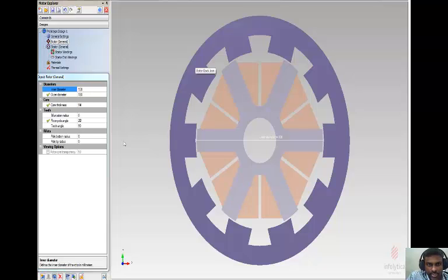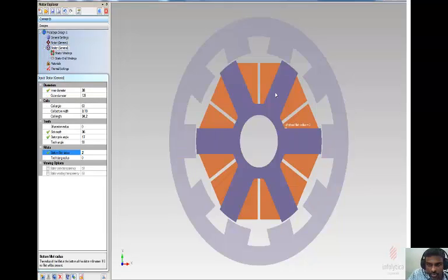The next thing is we are going to design the stator, that is this part, the inner part, which in this case is going to be the static part. The inner diameter is 38 mm. As I already told you, the inner diameter is the shaft diameter. It is 38 mm. The outer diameter, that is this one, excluding the air gap, is 126 mm. The coil angle is 60 degrees. Coil bottom width is this one.